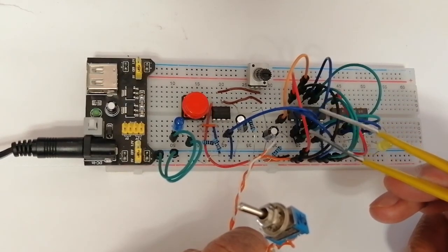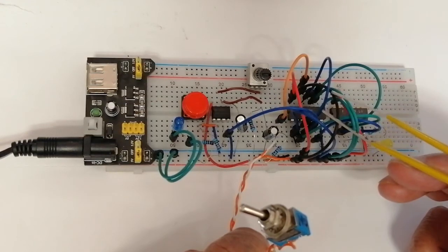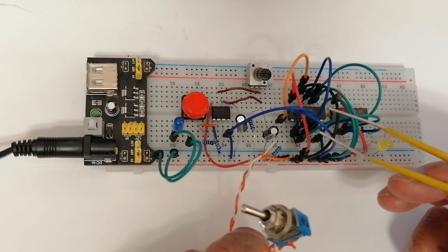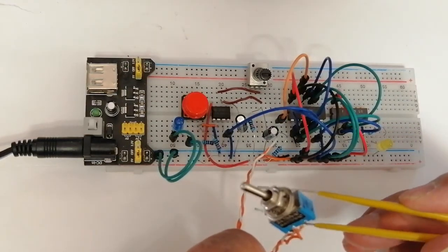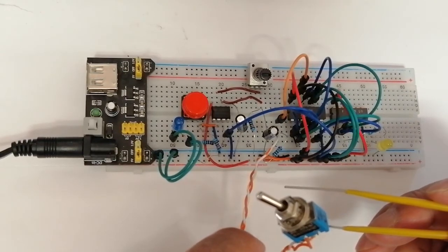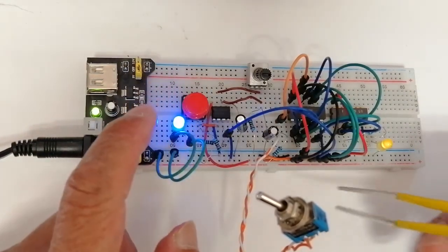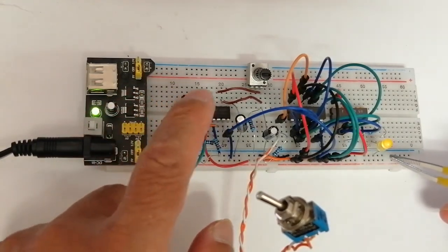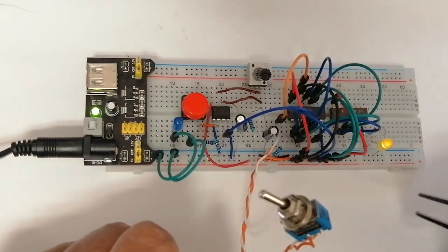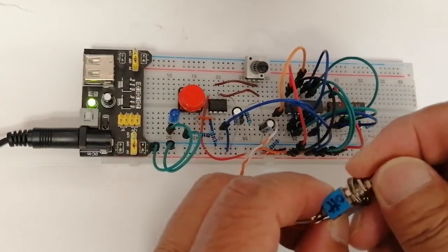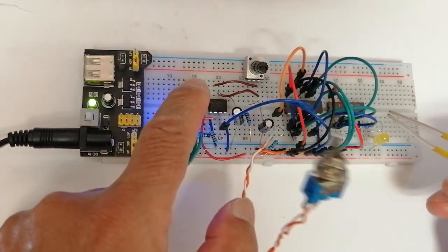So it's good practice to connect all the unused reset signals. It's usually made active low, so connect it to the high state, the 5 volt, so it's stable. Because when you try to measure some voltage and there's a slight movement, it's going to pick up and change the state. And this floating switch is the manual control whether to give high or low to one of the flip-flop inputs. So we give the first power shot. Okay, so this lights up. Second, turn off. Next clock, it's turned on. And this is right now off state, meaning one of the flip-flop inputs is high, so it toggles.